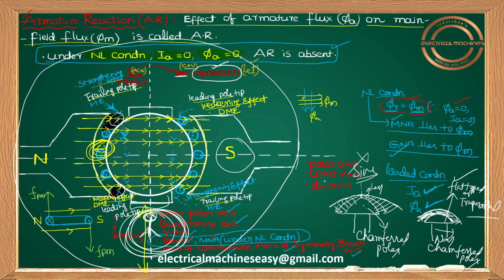In a DC machine, you have to prefer flat topped trapezoidal over sine wave, whereas in an AC machine we generally need a sine wave, because we don't want any harmonics. Therefore, in the alternator, we were using chamfered poles in the salient pole machine for making the flux waveform sinusoidal. But here in the DC machine we need a flat top or trapezoidal waveform, not a sine waveform. Harmonics will be there when compared to the sine wave, there is no doubt in that. But harmonics do not matter in a DC machine. If harmonics are there, there is no problem in a DC machine.